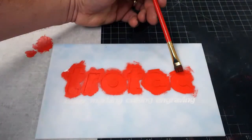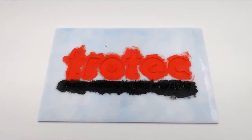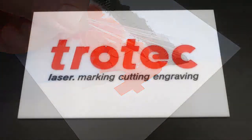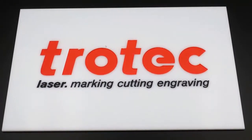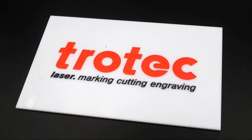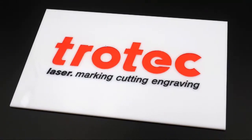So only the area that has been exposed from the laser, and in this case, I've just hand painted 2 different colors into the logo. And then once it is completely dry, you just go ahead and remove the mask. Liquid mask is nice because once it's dry, it performs just like any other mask. Peel that mask off for your finished, nice subsurface color-filled painted sign. So this is a great method for producing a surface, and so you don't have that reverse transparency. Maybe you're engraving onto the surface of the material.